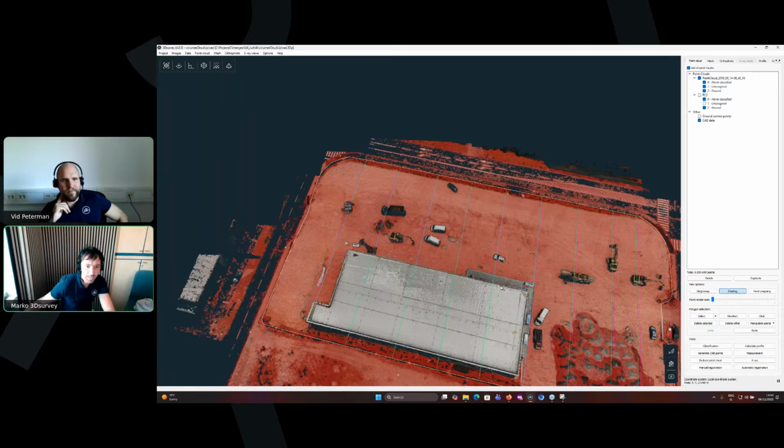Thank you for the webinar. Maybe this question is not on today's topic. Do you plan to integrate georeferenced panoramas from laser scanning so that we can measure and draw directly on photos? It's not today's topic because this was already done in the previous update. If you export your point cloud with panoramas in E57 format, those panoramas will be visible in 3Dsurvey. And if you check the previous webinars we did, I think that was the 3.1 update, you'll also see how it works.